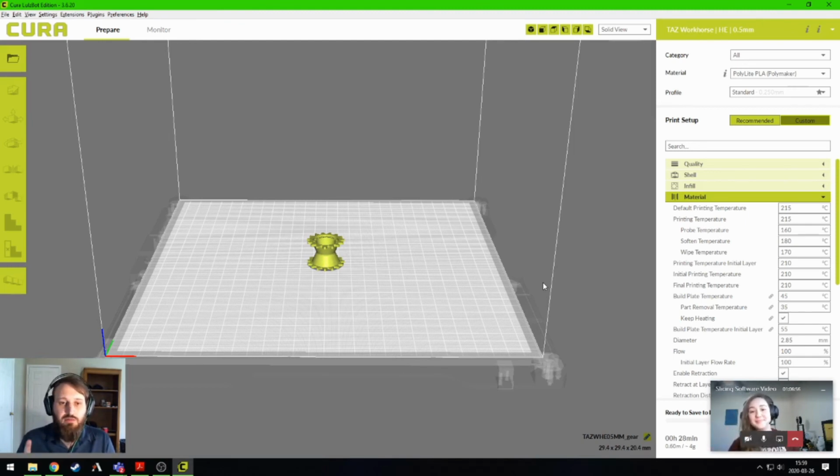But a lot of times the manufacturer will provide, or hopefully tell you, the information like, here's your print temperature range for this material that we're using. In PLA, usually I see like 190 to 220, 230 on the high end or something like that. Does your printer have a default that you use? For the print bed? No, for your print temperature. So for your nozzle temp. Print temperature. Oh, for the nozzle. Sorry, I don't know where I got the print bed from.